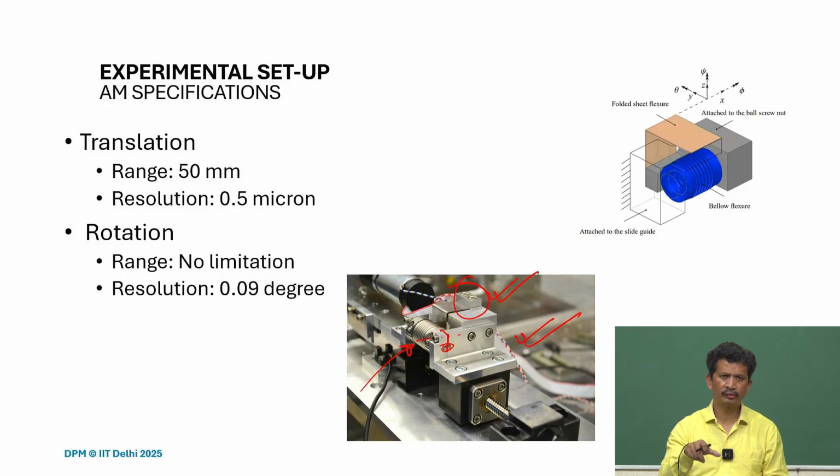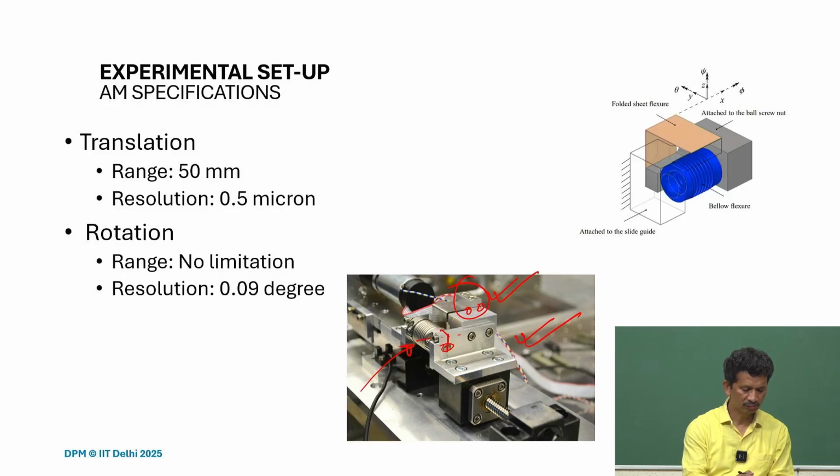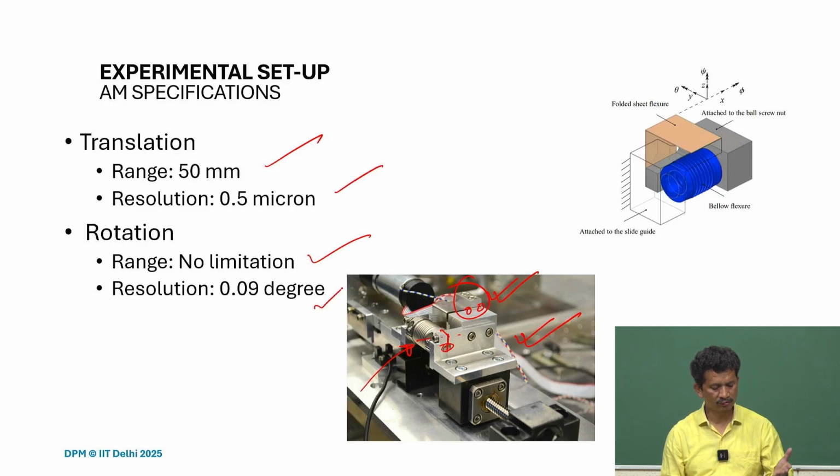We have to also design those clamps properly. So you can see the small edges there which is holding it. So very important. So yes, ultimately this is what we achieved. So based on the encoder's resolution, we can also find the translation resolutions, what it would be.